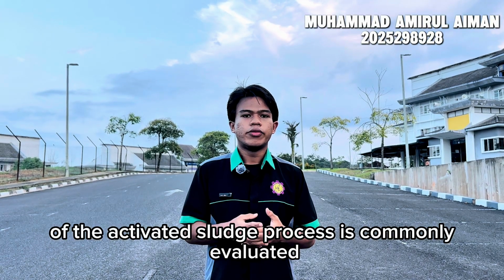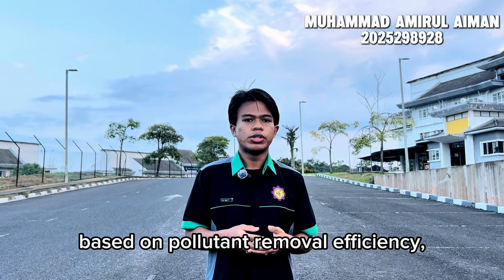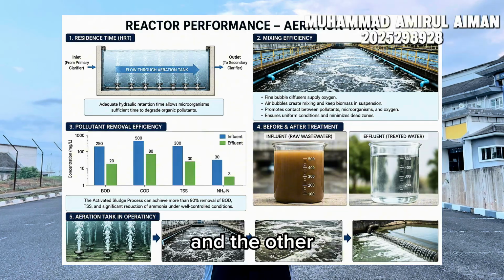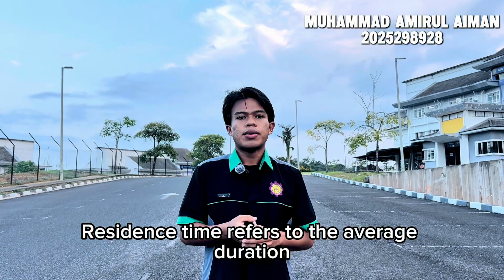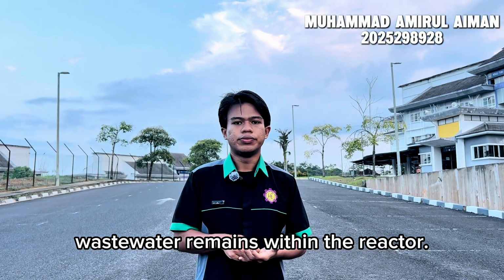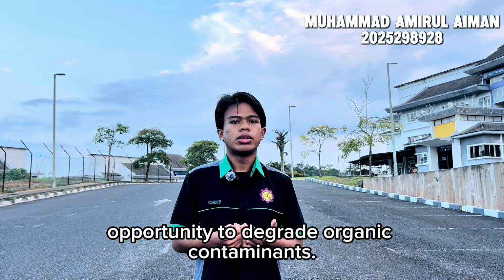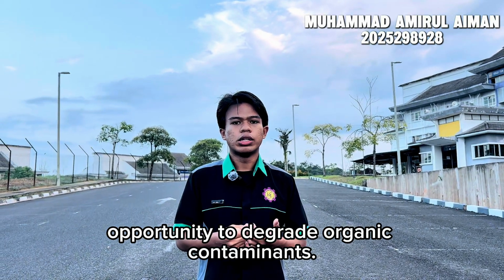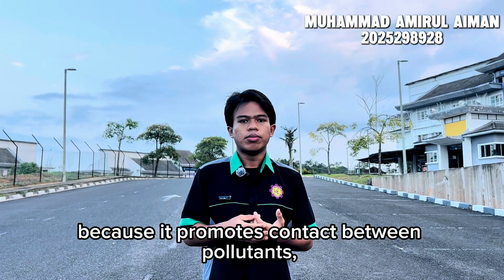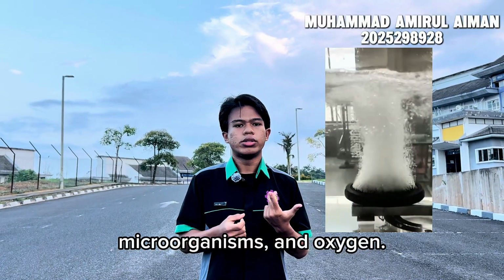The performance of the activated sludge process is commonly evaluated based on pollutant removal efficiency, residence time, mixing effectiveness, and others. Residence time refers to the average duration that wastewater remains in the reactor. Adequate residence time allows microorganisms sufficient opportunity to degrade organic contaminants. Mixing efficiency is equally important because it promotes contact between pollutants, microorganisms, and oxygen.